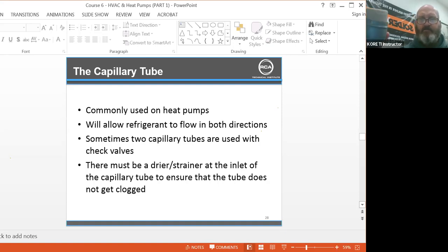Here I have a cutaway. If you guys want to see what a liquid dryer looks like, we cut a dryer in half. Here's what the actual desiccant looks like on the inside. This block wall. It's going to be just like you guys out there doing market work or refrigeration work, where you're using something like an RC4864 dryer shell. It's the same style. And here you can see inside, that is the brass screen on the outlet. Usually on a bidirectional liquid line, there'll be two brass screens, both in and out. But that's what a dryer shell looks like.